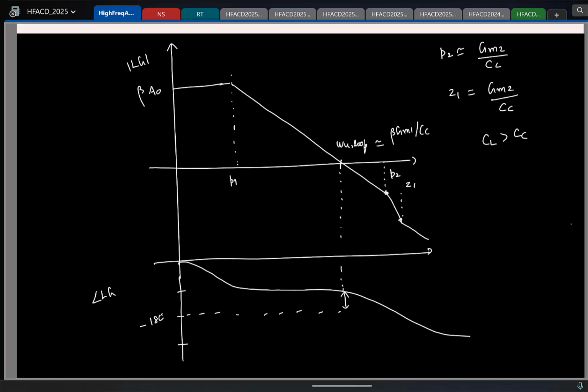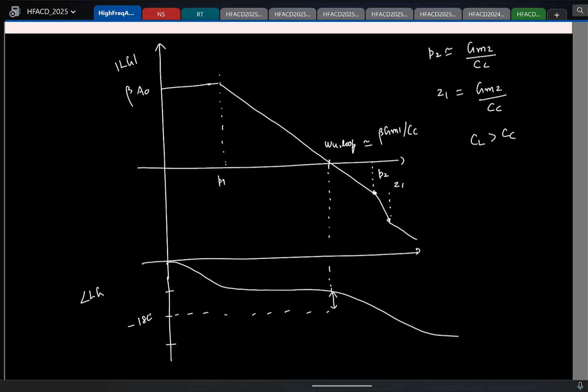So here is where sometimes people can get confused. So let us say now I consider this situation wherein the second pole is occurring somewhere here. Okay, so which means the magnitude plot will do this. Second pole is occurring at this point, so it will start to drop as minus 40 dB per decade, and then the 0 comes. Let us say, maybe I'll draw it.